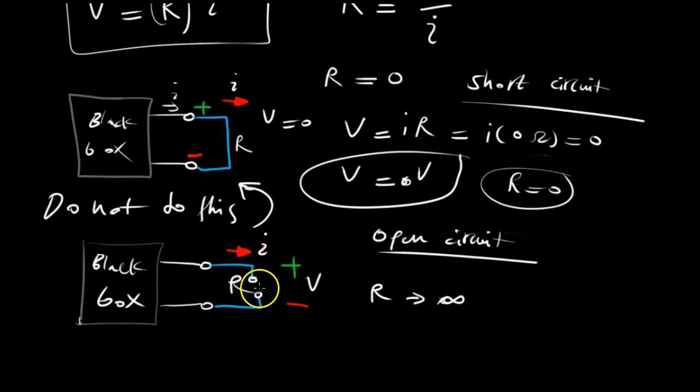That is an approximation, because when you have a wire here and a wire here, you would need voltage to approach infinity to ionize the air molecules to produce a conductive path for the current to flow, which is what happens when you have lightning. You have very, very high voltages produced by very strong electric fields that ionize the air molecules. They pull out the electrons, and that allows a conductive path. So when you have an open circuit like this, we say that resistance is approaching or is equal to infinity.